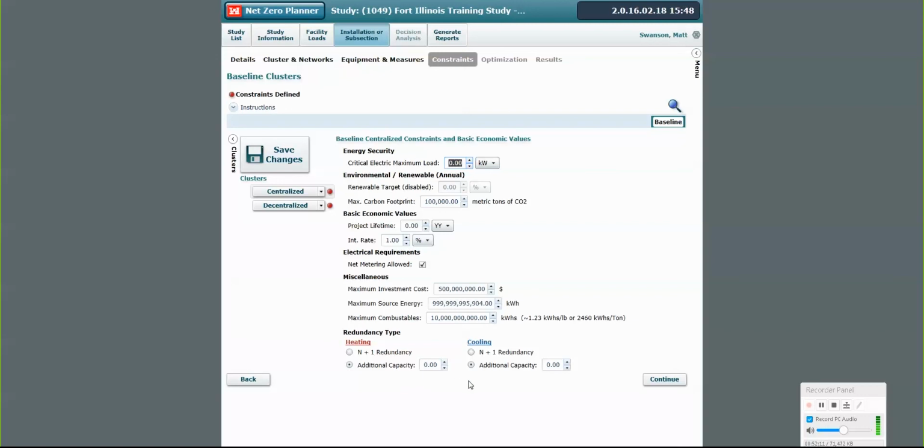These are things that we're going to get into more again with the alternatives, but basically, if you're going to look at getting closer to a design of a central plant, you might want to do something like N+1 redundancy, and what that basically means is you can meet your peak with all of your equipment while one piece is offline. So basically your largest piece of equipment can be offline and you can still meet your peak. That's a standard type of redundancy that might be required for a central plant. And that might be so that you can do maintenance or something else, but if you're really going to design it, you're going to buy enough equipment to meet that requirement.